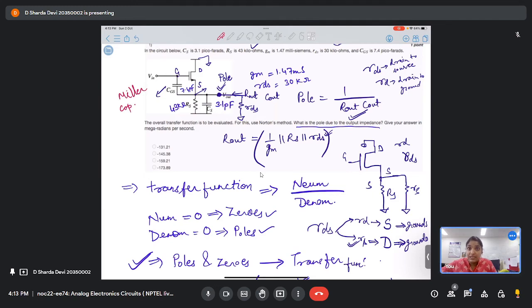Whatever impedance you have in between, a certain part you'll see in the input node and a certain part in the output node. In the input side you'll see gain times the capacitance, and in the output side you'll only see that capacitance times 1.